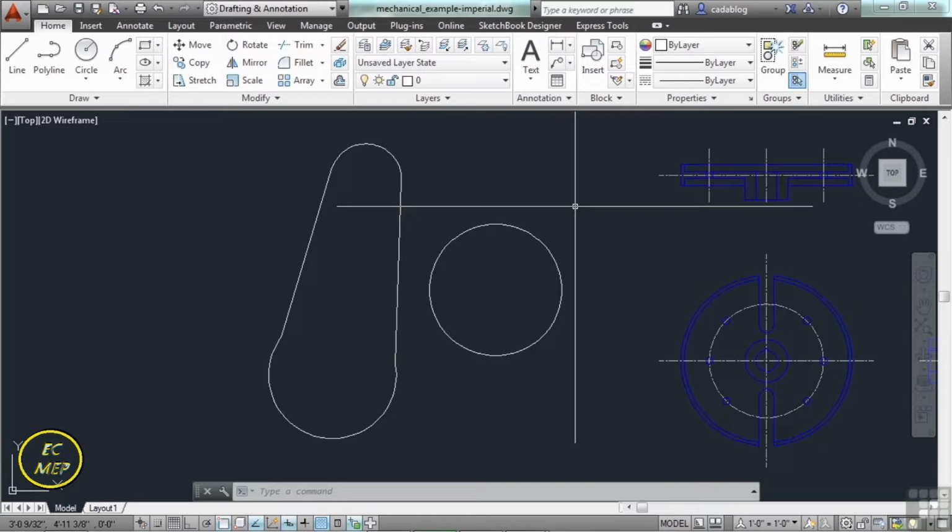When you put something on the command line, then you can use different things. Typically though, you'll be able to just enter in your command. Type it in, just start typing wherever you're at. And when you're done, press enter. That starts the command. Another option besides the enter key is the space bar. The space bar in AutoCAD, unless you're typing in text, functions just like the enter key. So when I'm starting a command, I can press space and that's enter.